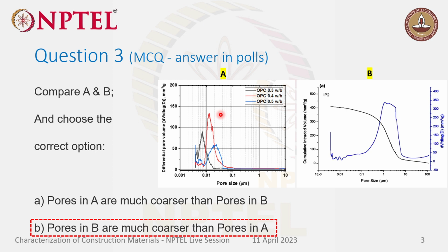When it comes to structural design, we say weak beam and strong column, right? It doesn't mean that the beam should fail, but the beam can fail, while the column should never fail. In that way we design the building, because if the column breaks, the whole unit will break. Similarly, in masonry structures, they consider that the brick should not fail, but the mortar can fail if it's subjected to a marine environment or strong chemical exposure. It can happen in that way.